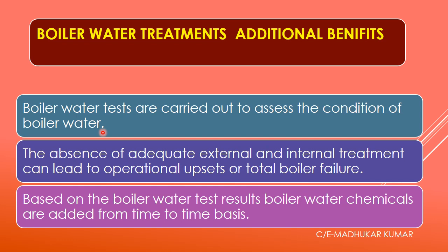If you are on a dry fleet, then you may be doing the testing on a weekly basis, but on tankers and all you have to do it on a daily basis. So you have to know the actual condition of the boiler water, because based on that only you will be able to take corrective action, either putting in more additives or chemicals, or blow down, whatever actions you can take only if you do the test. The absence of adequate external and internal treatment can lead to operational upsets and total boiler failure. So this is the end result, which is to say that if you are not doing this, then it can finally lead to boiler failure.